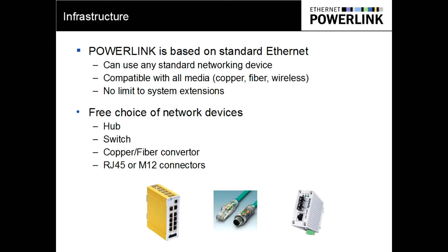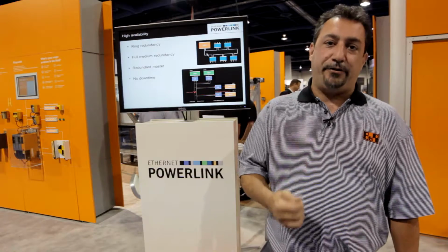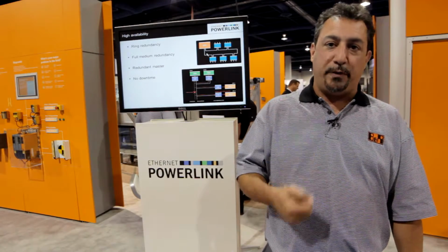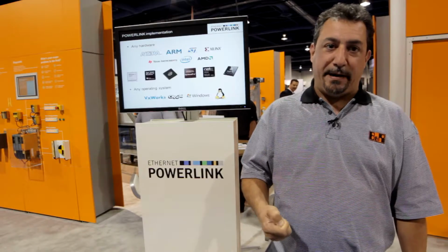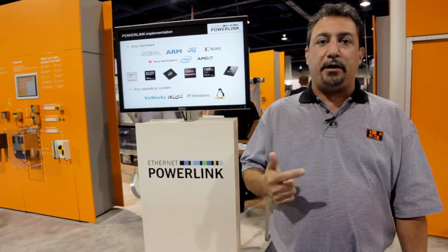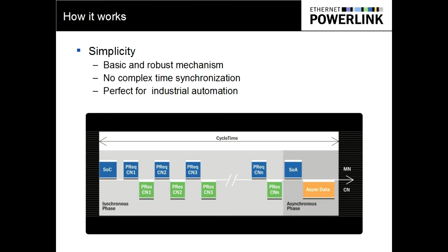POWERLINK is based on standard Ethernet, which means that the standard does not muck around with the frame. It is a standard Ethernet frame, and that means that you can use a standard hub or a switch to control the Ethernet packets. The real-time behavior in POWERLINK is exhibited because the bus master, which is usually the PLC,